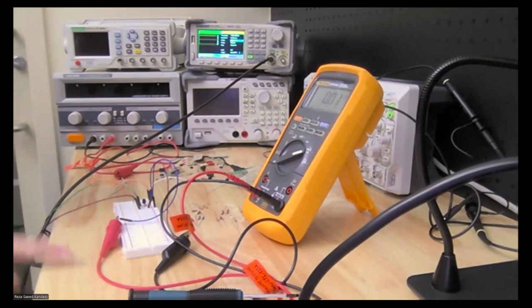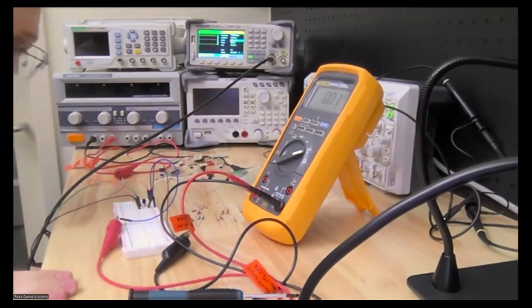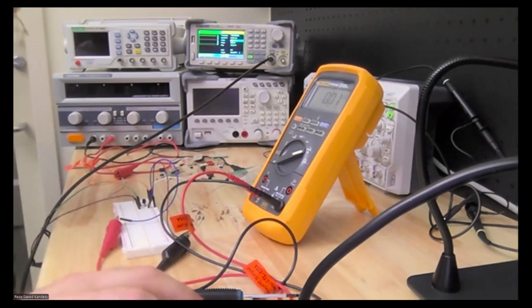Now, if you set different VGS and measure the current, the Kn that you see for each of those samples is going to be slightly different. So what you can do is average them out, find the mean value of those Kn and say, okay, the approximation is that mean value. So I'm going to consider the Kn equal to alpha or beta, whatever you calculated based on your measurement. So this way, you can also measure that Kn based on your experimental setup.